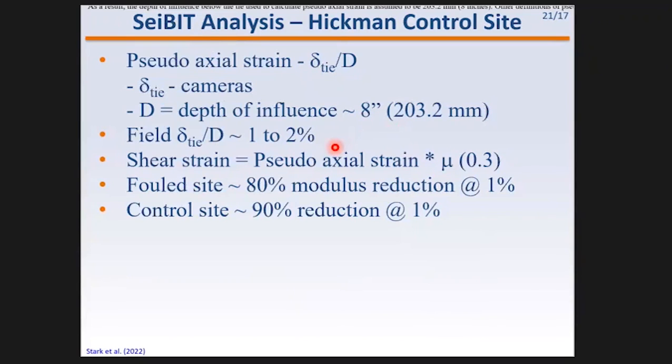And I think that's a good way moving forward, looking at how the system's performing in terms of a strain measurement instead of, say, a displacement. Okay, so this is important because we're going to have to use what's called a modulus reduction relationship. I know, you're thinking, geez, what the heck is that?